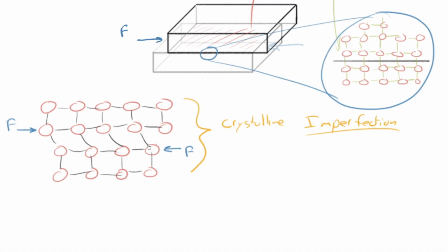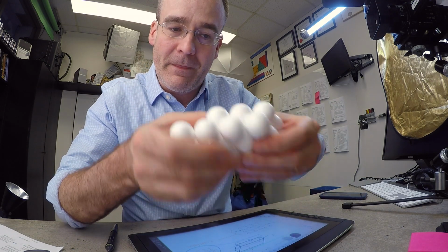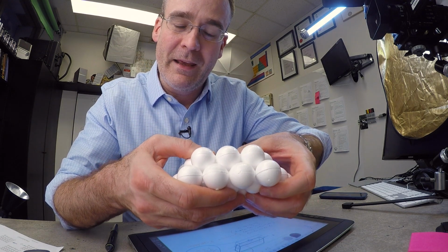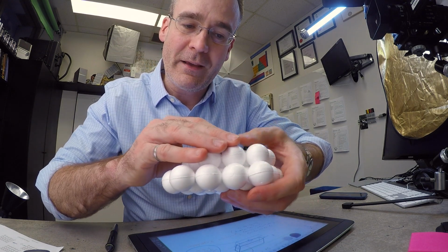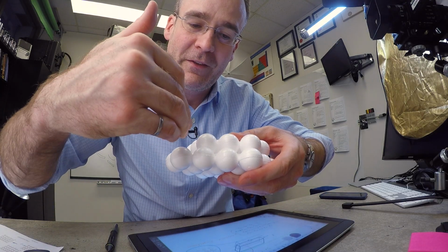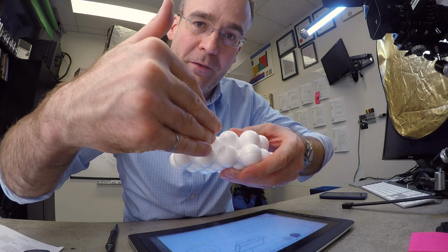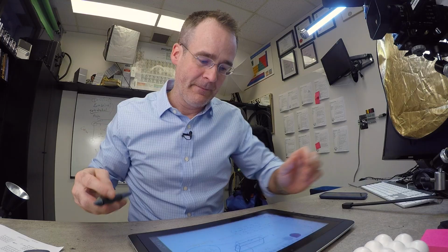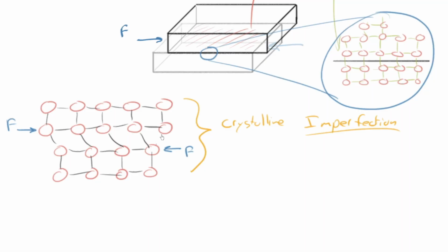So the end result is actually still the same, that this plane of atoms has moved to the right, this one has moved to the left, as we illustrated up here. That is to say, this start and end position is correct, but they don't all move together like this. There's actually these imperfections that allow just one row of bonds to break at a time and reform. Again, if I can kind of animate this a little bit in a very basic way by just undoing here and going back and forth.